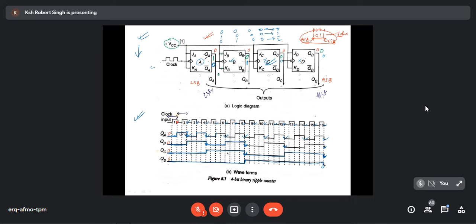Can you understand? So this is the waveform, and when you see, it is 0, 0, 0, 0, and this is 1, 0, 0, 0, and this is 0, this is high 1, this is 0, 0, and this is high, this is 1, this is also 1, this is 0, this is 0. So this is 0, this is 1, 0010 is 2, 0011 is 3. This is decimal 0, decimal 1, decimal 2, decimal 3. So it looks like a counter. It is counting. Is it okay?